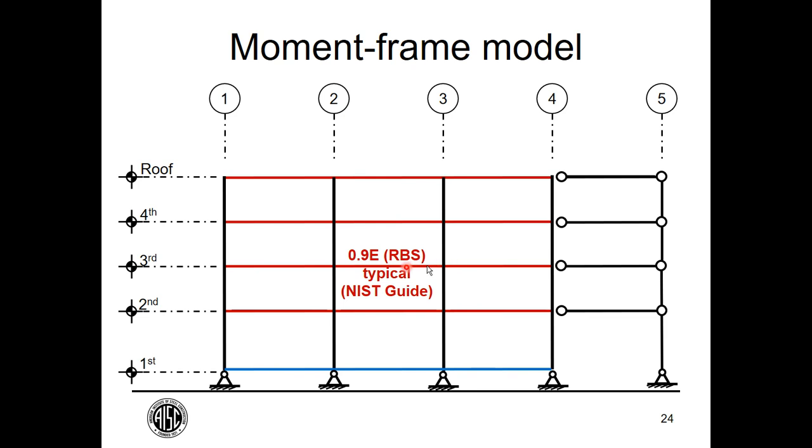The recommendation is if you take the full reduction of that dimension C up to 0.25 times the flange width, then you have essentially 90% of the flexural stiffness of the beam. That's a reasonable assumption. So that's what we have in our analysis model. We also have, for the moment, a pin base, but with a flexural member here reflecting the flexural rigidity of the foundation.